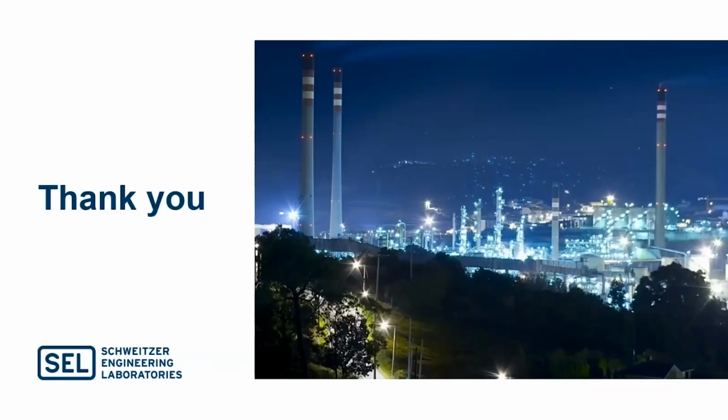There was another remedial action scheme that we implemented for the country of Peru, where it was all based on synchrophasor data. We're looking at positive sequence voltage angle across multiple substations, and based on that, we're detecting whether a line was lost or any power system event, and taking action based on that. So yes, there are actually some systems in place that utilize synchrophasor-based data as well.